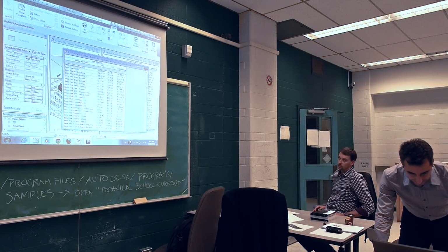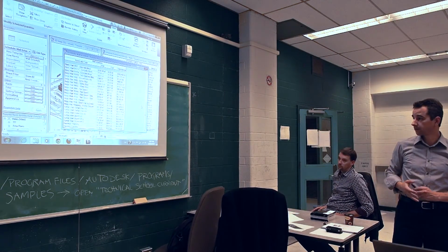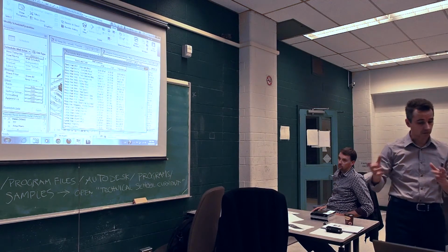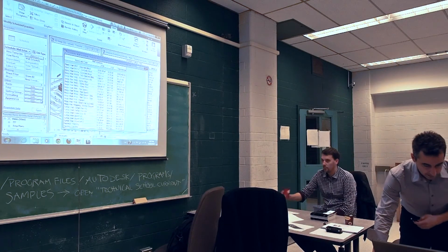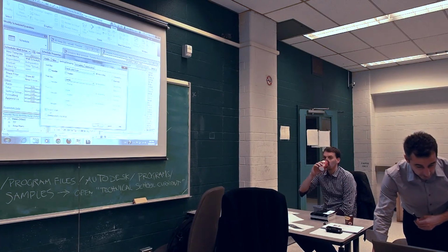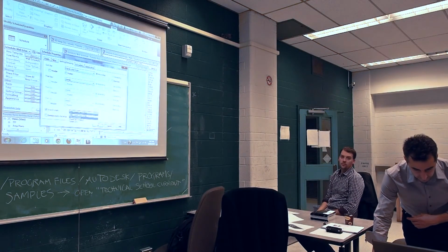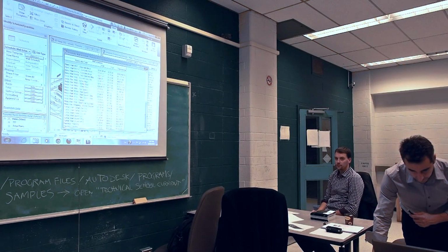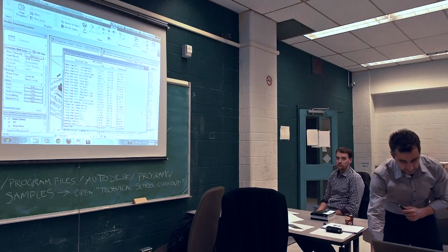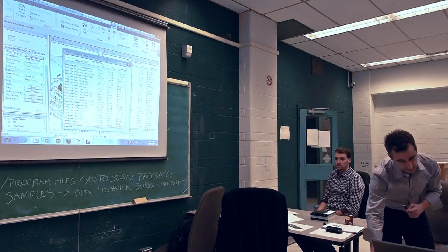Let's see the result. This is the result. Would be nice if at the end, at the very bottom area of this table, I would get a total, so I know how much money I'm spending on walls. So I go edit again, and in sorting grouping, I would like grand totals. And I have options. I want to go with title and totals. So at this point, I have my schedule, which should be exactly the same as the other.